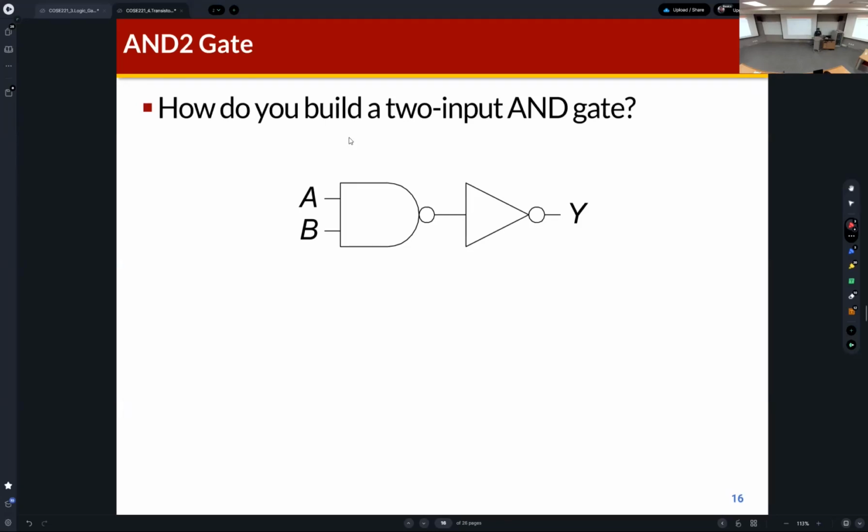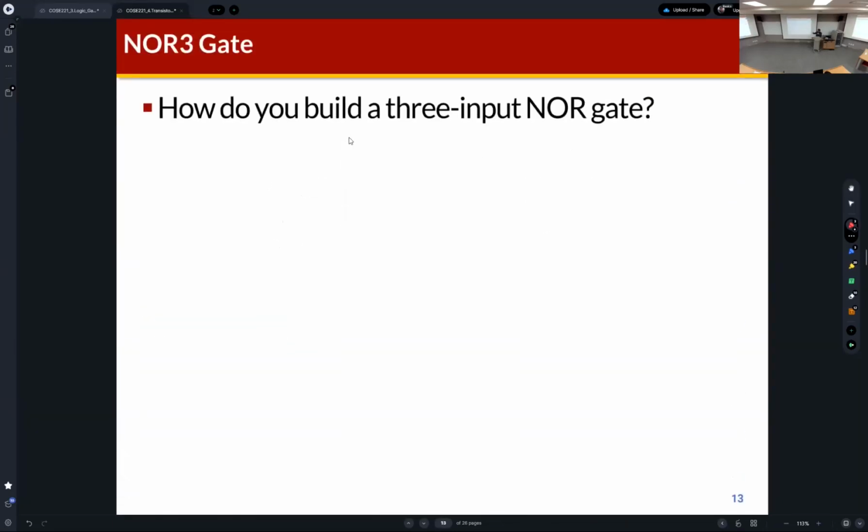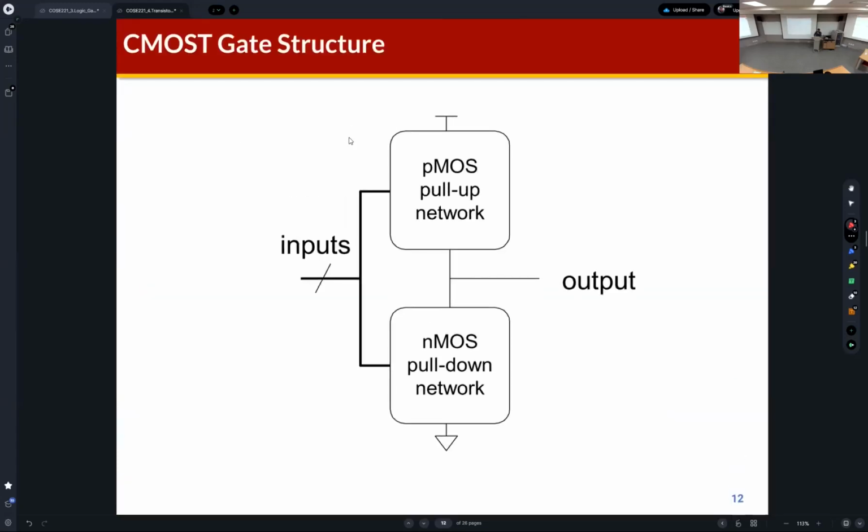So why do I explain this? We can easily, straightforwardly build the NOT gate, NAND gate, and NOR gate using CMOS transistors, because the gate is directly connected to the input signal without a bubble. Okay, the NMOS transistor is connected to the ground, and the ground means 0. So we can control the connection and disconnection of ground using the MOS transistor.